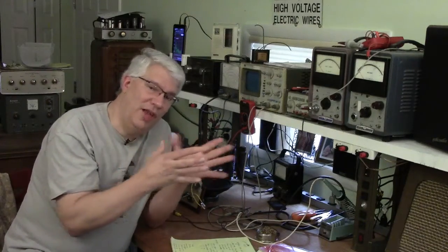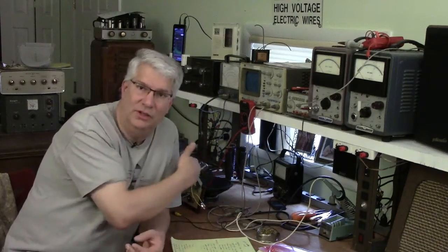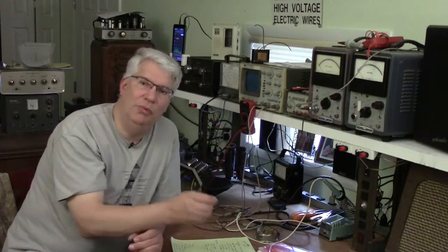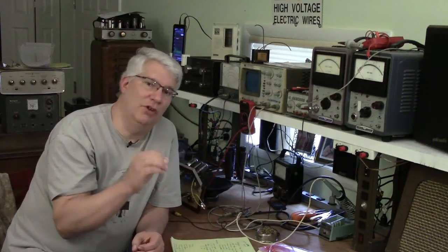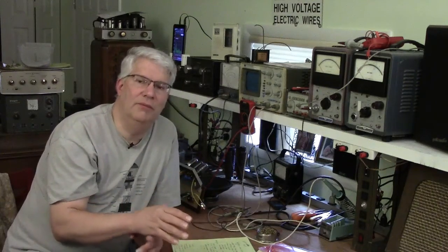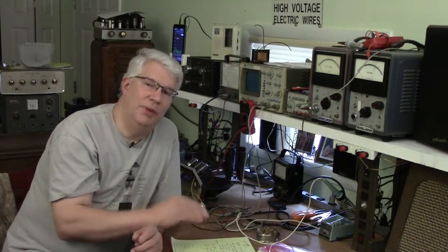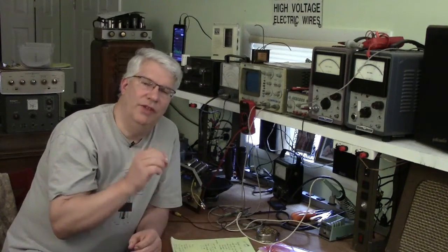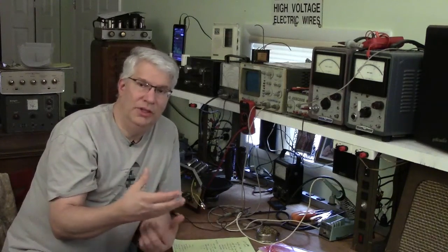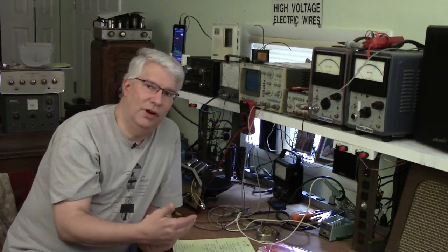And then once we're done with all that, we're going to wire this back up again, in the software as well as on the bench. We're going to put it back in pentode mode, which allows us to get more power output. We're going to look at the implication of going from a triode circuit to a pentode circuit with the same tube, everything exactly the same, and figure out what the harmonic content of a pentode circuit is, and see why it's different. It ultimately has different distortion characteristics, and that's not a bad thing for a guitar amplifier.